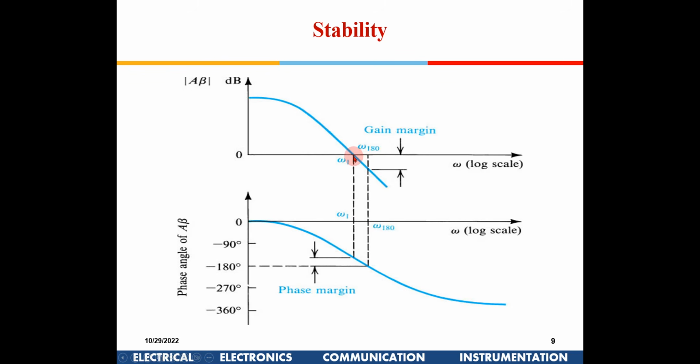Means, like, when the gain is going negative. Yeah, when the gain is 0, where gain is 1 or 0 dB, if it has made 180 degrees by then, it will be stable, or it has made 180 degrees before that itself. No, non-stable, I am saying non-stable. What would the condition be for non-stable?